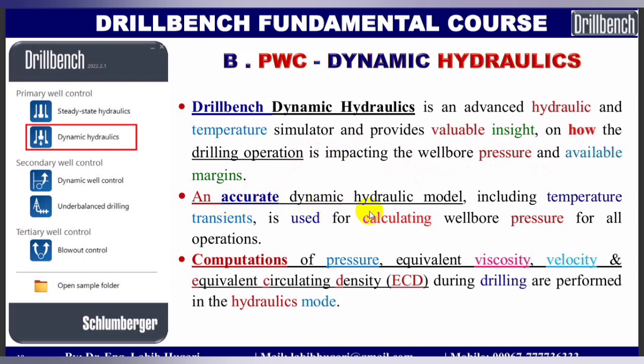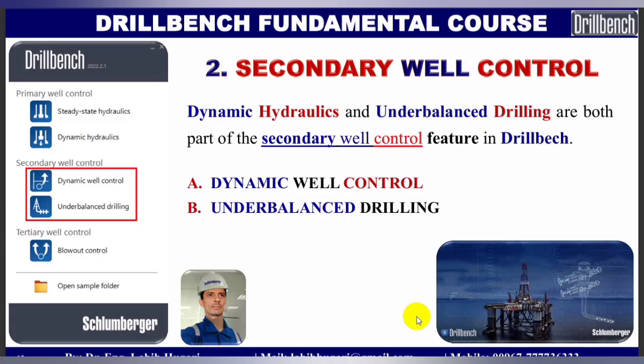An accurate dynamic hydraulic model, including temperature transients, is used for calculating wellbore pressure for all drilling operations. Computations of pressure, equivalent viscosity, velocity, and equivalent circulating density during drilling are performed in the hydraulic models.